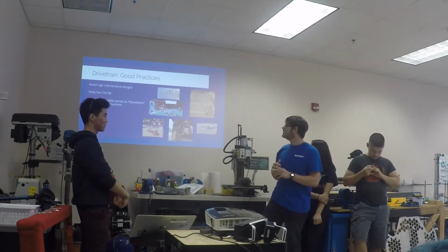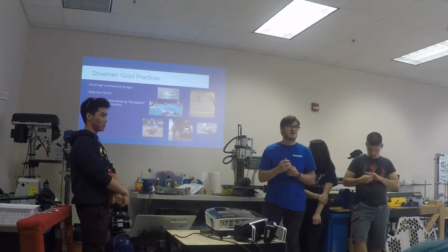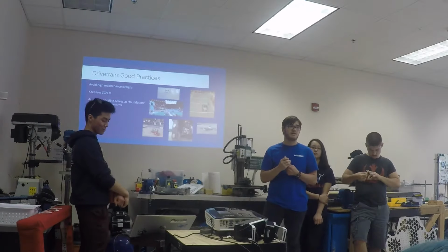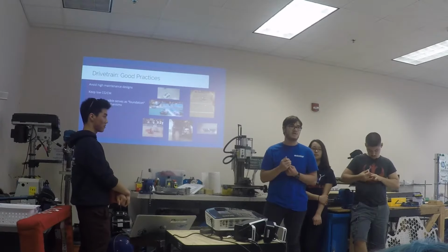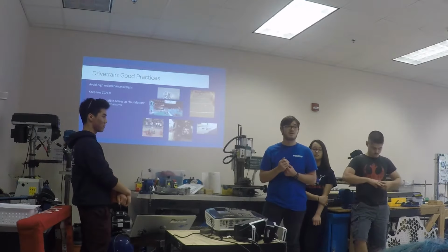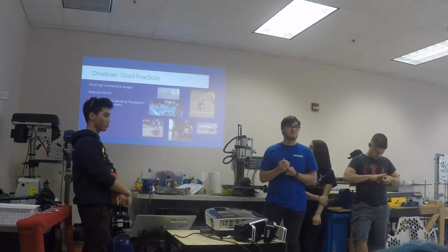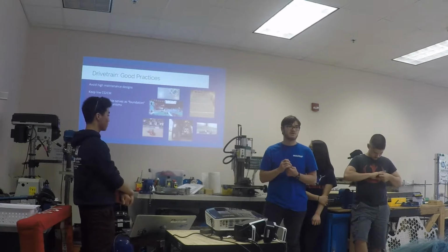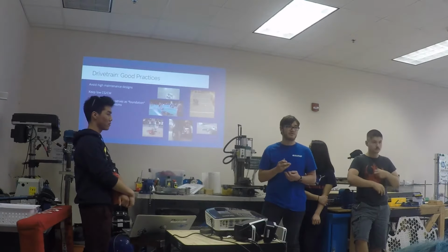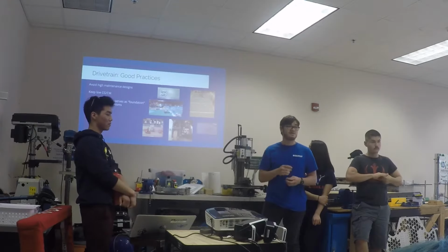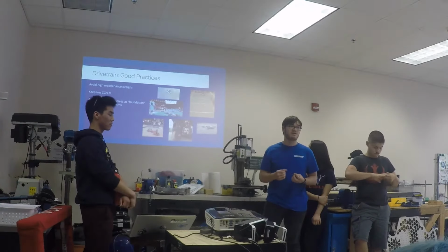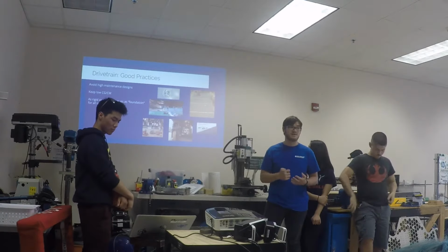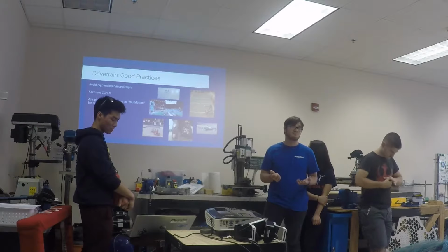For your drivetrain, you avoid high maintenance designs. Your drivetrain needs to be able to function repeatedly over and over and take a beating because it's what's going to be smashed into walls, game components, and sometimes other robots. It's also at the very base of your robot, so it needs to be a very strongly constructed piece. It holds up everything in the literal sense that everything is built on top of it. So everything is quite literally relying on it. It needs to hold up, and if you're repairing your drivetrain all the time, you're having issues, which means you can limit your ability to do anything in the game because it's how you move. If you can't move, you're basically dead in the water.